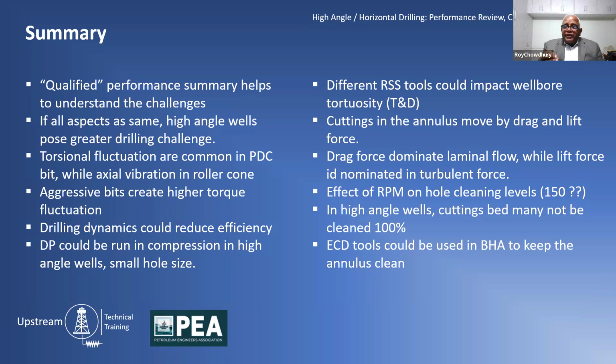Bit, obviously, if it is a PDC bit, based on the hardness, you would select the cutter type. In the bit world, the cost of the bit goes astronomically high based on the cutter. There are some cutters which are impact resistant and cutters which are wear resistant. If you are drilling through a very abrasive formation, you would expect wear, so your cutter type selection should be wear resistant. It is not that easy.